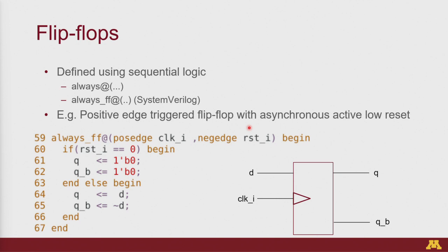So this won't exactly be how the flip-flop will be. In reality, this code would, like you said, create two flip-flops, right? But I've just written it here to represent what you normally view as a flip-flop. But yes, the code for this would actually implement two flip-flops. Usually you do not implement both the positive and the negative logic. You just implement whatever logic you want, and the tool figures out which one to use, right?